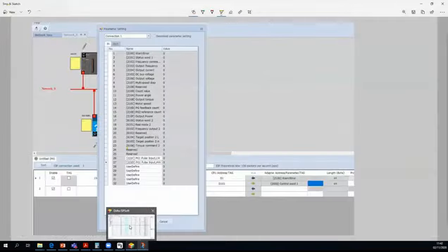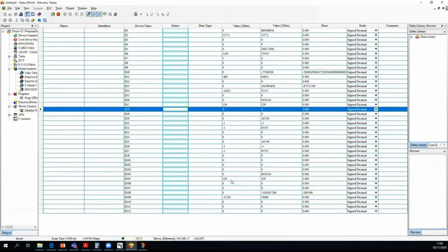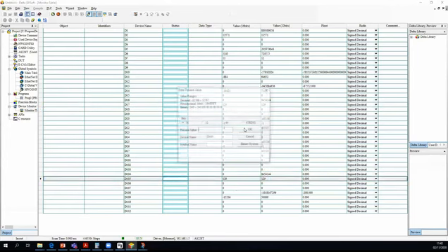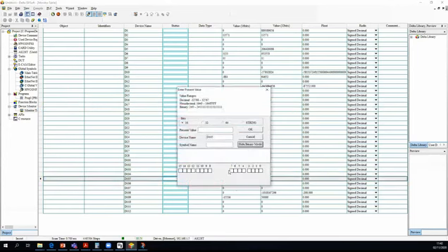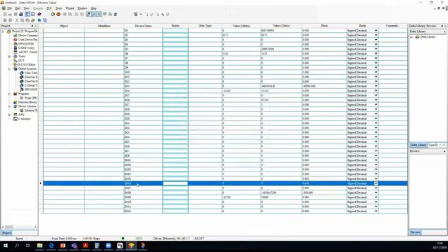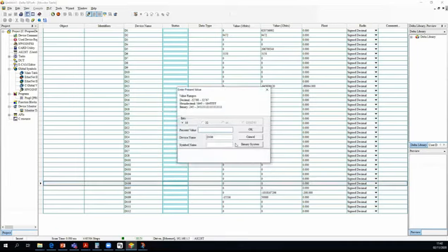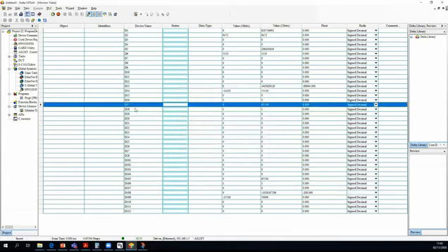So firstly, I will stop the drive because you can only change the operating mode when the drive is in stop mode. So just set it to 0. Now I'll set 6001 to 1 for positioning mode. Okay, so now I can also read it here.